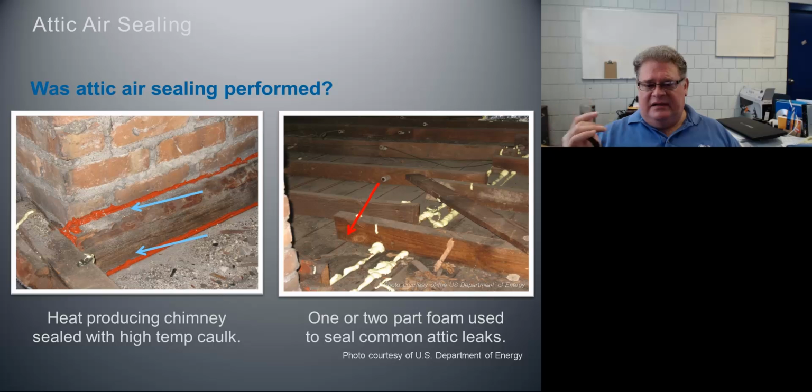Here on the right hand side, we have a one or two part foam that's used to seal the top plate. Is this good or is this bad? This doesn't appear to be too bad to me. We do have foam used on the top plate, that's acceptable.